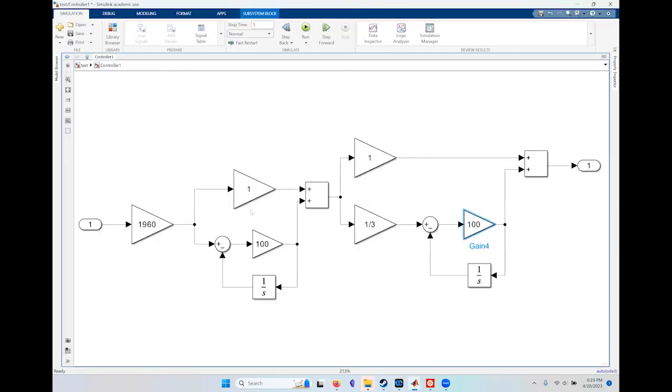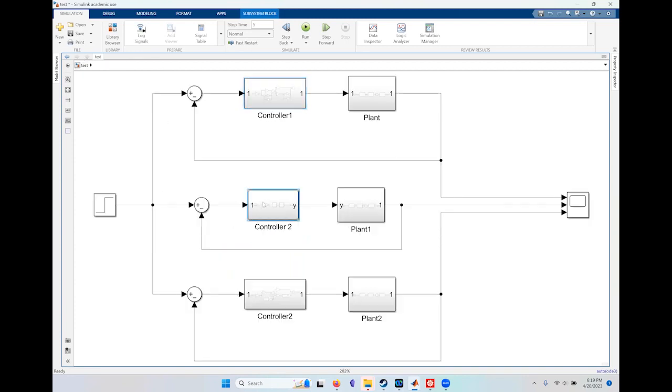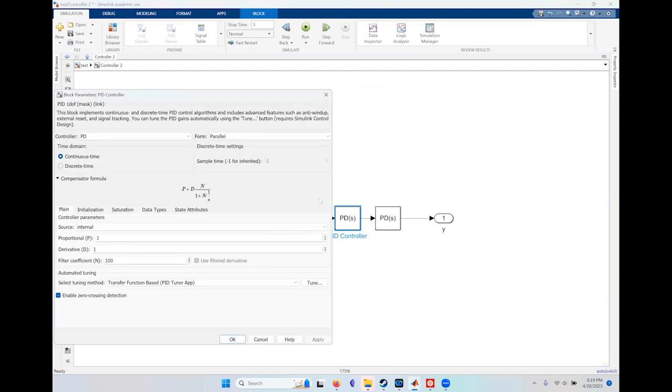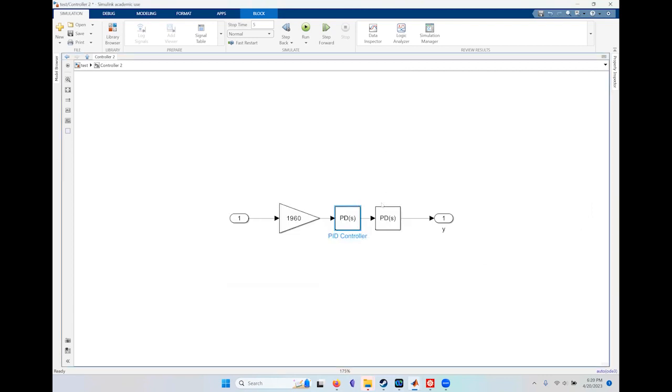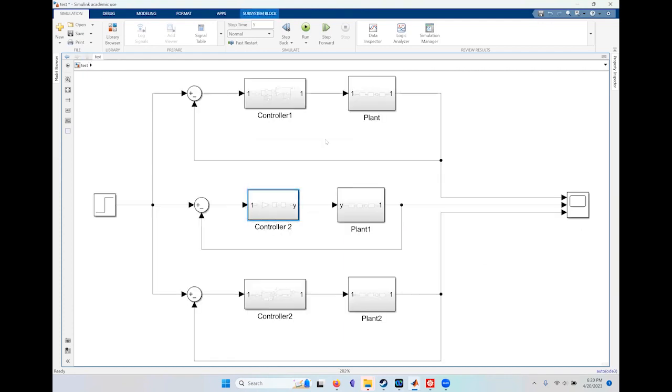If you want to use a differentiator, use something like this, where you add a pole already, and then you write the differentiator this way, or use one of those blocks if you want. I typically don't like to use those blocks, especially when I am learning or you are learning, because those blocks kind of hide stuff from you, right? And it makes it harder to learn. You can use those blocks only after you are well established in using this tool.